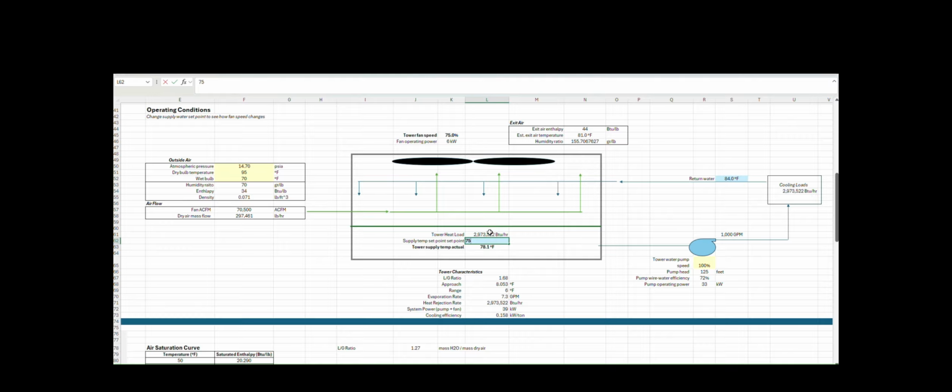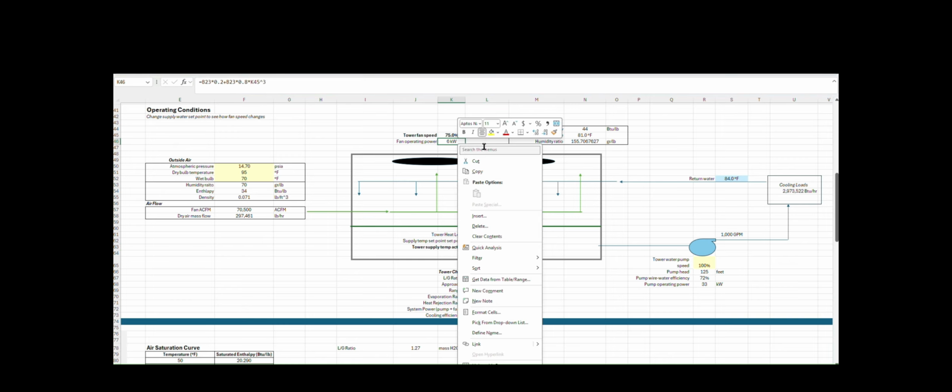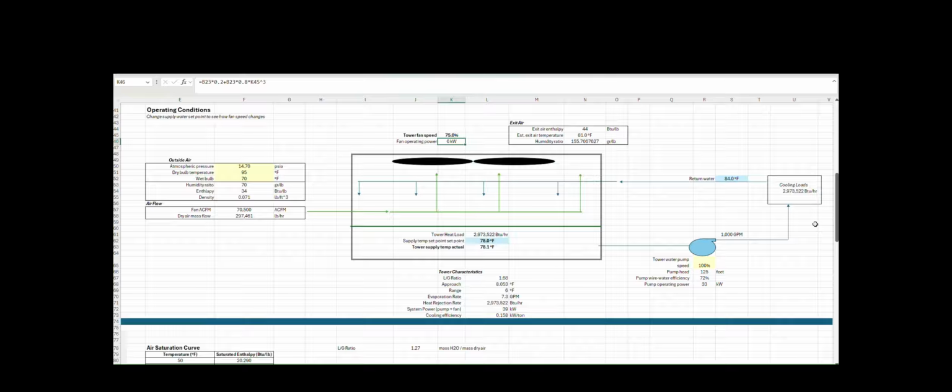Because if we're running at 100% speed, if I just force this to a low set point that I know it won't achieve, I can make 77-degree water. So let's say that if I were to make, instead of 77-degree water, just a degree higher, my fan power dropped by 6 kW. Maybe my chiller power only drops by 2 or 3 kW. So I'm not going to get into a whole optimization problem here, but just saying that there's some control strategy on your set point here that should be considered, and it's not always going to be the same depending on the cooling load that's being served.